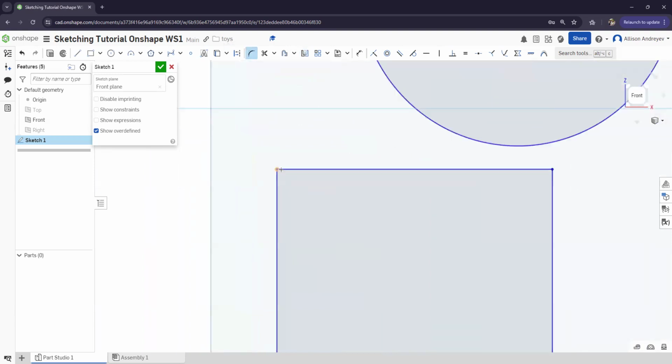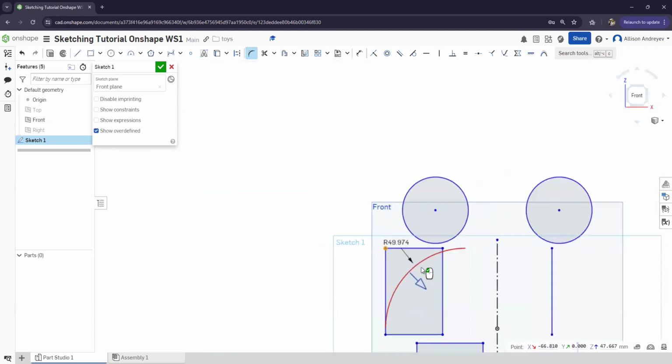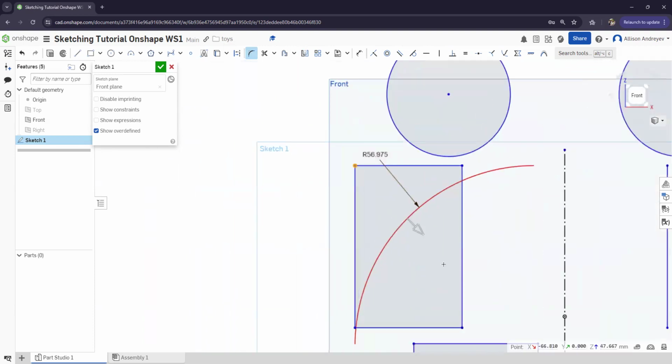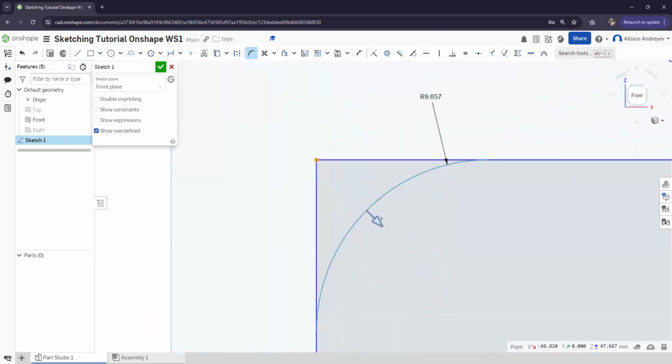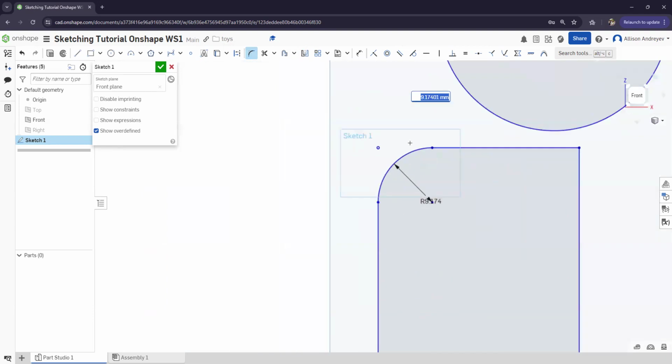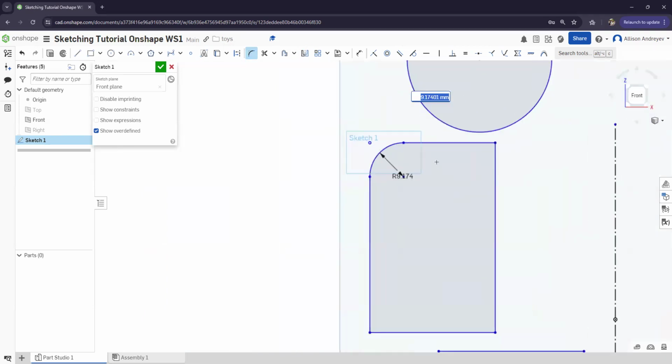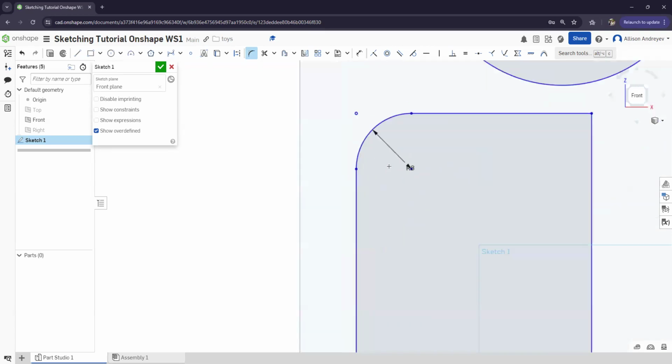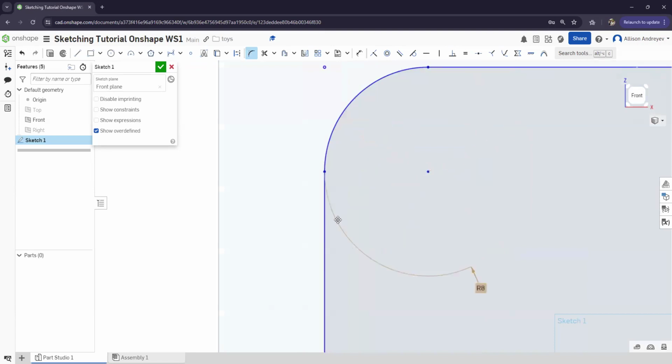Next I'm going to show the fillet option. You would select the fillet here, and select a corner, and what it lets me do is round that corner. There are obviously limits to how far around we can go, but I can choose a radius and effectively round the corner. Let's just say that's good. Then I can left click and the fillet is confirmed. I can even customize the radius of the fillet after I finish, so I can change it that way.